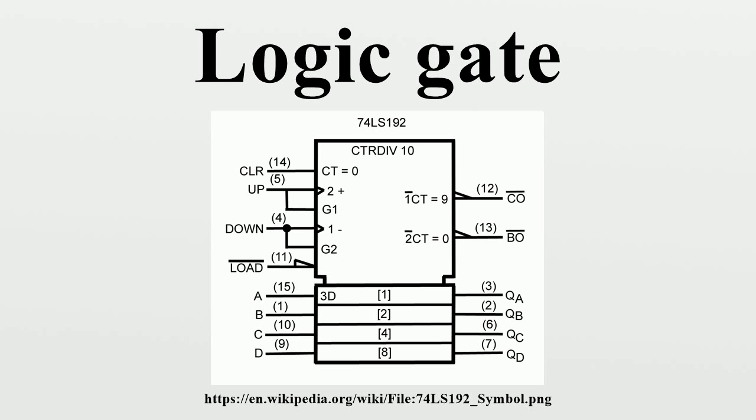Electronic logic gates differ significantly from their relay and switch equivalents. They are much faster, consume much less power, and are much smaller. Also, there is a fundamental structural difference. The switch circuit creates a continuous metallic path for current to flow between its input and its output. The semiconductor logic gate, on the other hand, acts as a high-gain voltage amplifier, which sinks a tiny current at its input and produces a low-impedance voltage at its output. It is not possible for current to flow between the output and the input of a semiconductor logic gate.